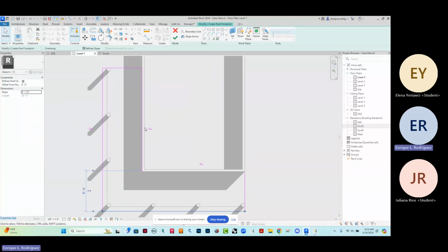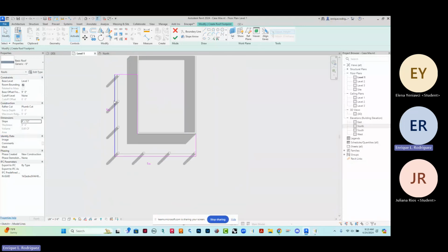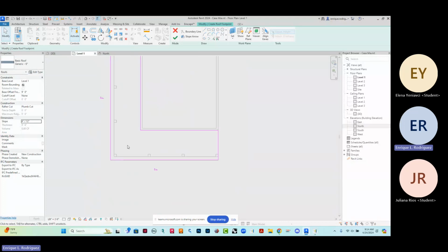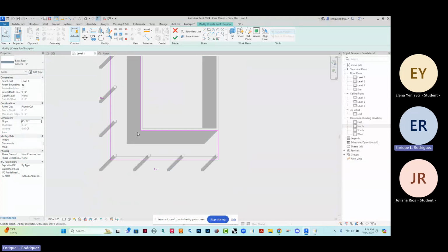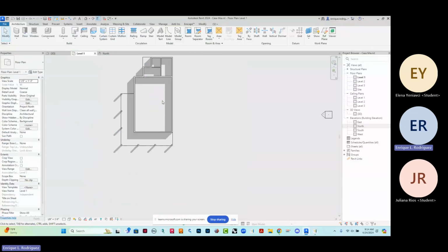I actually want to remove defined slope back here and back here because I don't want that going up in any direction. So I'm going to remove those 2. And now the only place it should be sloping up is from this edge and this edge. So it's going to be sloping up here and sloping up here. Now, if you remember, I made the porch, unlike what the reference material says, the same depth on left and right. And the reason I did that is because I want the hip set right here to hit on the corner of the second floor.